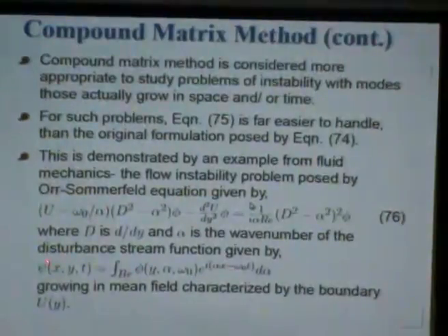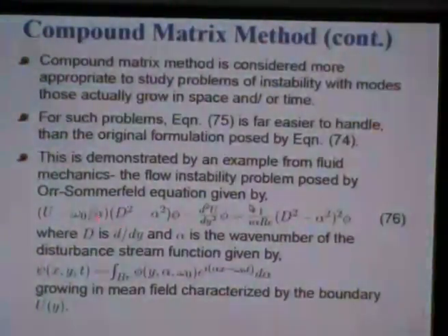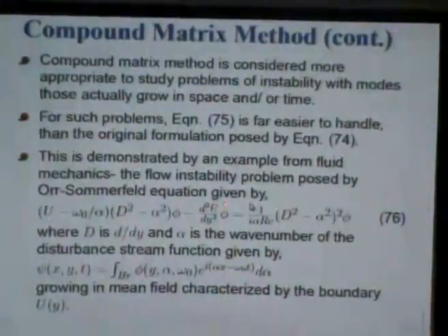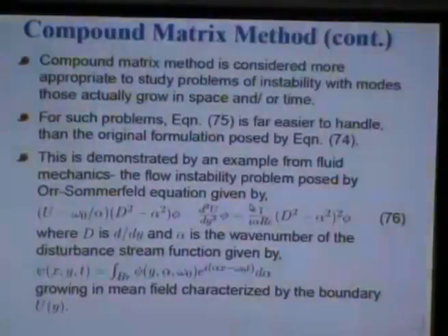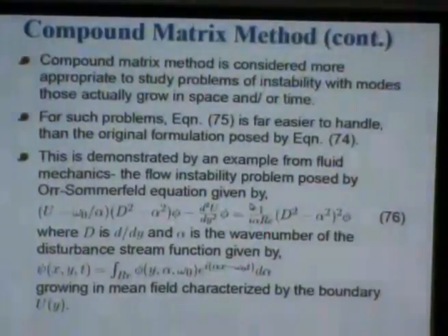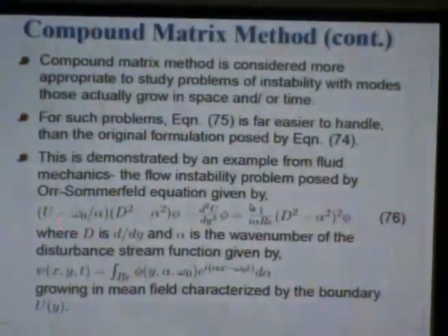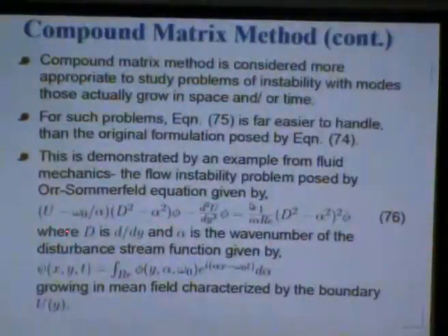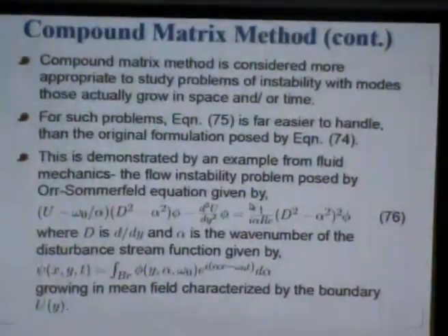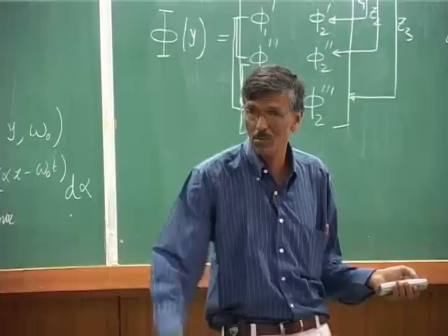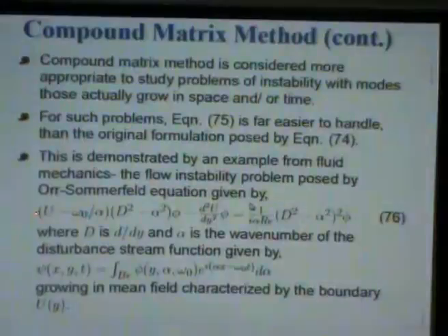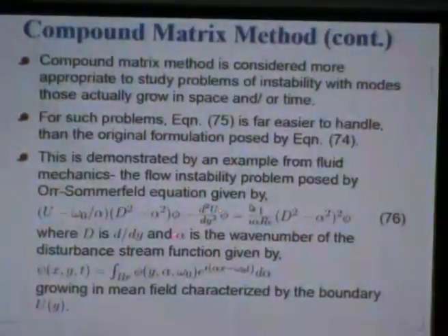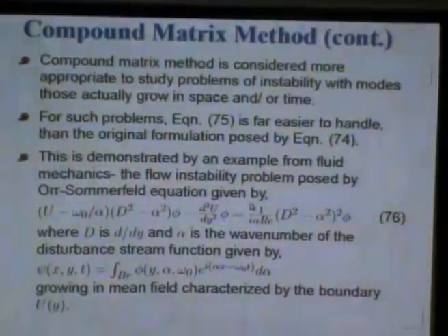And that is what this equation tells us, that the mean flow u and its second derivative are involved. So, you can see, that is what I was telling you, that in all disturbance evolution equations you would have input coming from the mean flow. It does not just evolve by itself. There has to be a source of energy from where it will tap its energy. So, that is how these mean flow terms come into this equation, and these are various mechanisms.